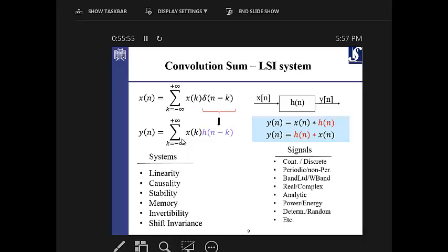That's a sample. Fourier transform of these things, I would actually have complex values too. It won't be zero, so I'll have to play with that too. Exactly. Okay. If you have a complex signal, definitely you will have a complex Fourier domain. If you have a real signal, again you will have a complex Fourier domain. But the spectrum is symmetric. For this case, it's not symmetric.